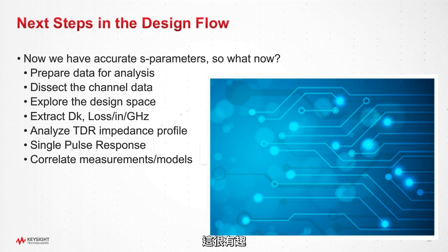So this is interesting. Finally, one of the most important things that I think we should be doing more of is correlating measurements with models. The power between this simulation, guessing what the performance will be, building a prototype, and then comparing the measurement of the prototype to the simulation is extremely powerful and gives us a lot of capabilities of hacking the backplane or things of this nature. So these are all future things that we'll be doing once we get these little golden nuggets of accurate S parameters.